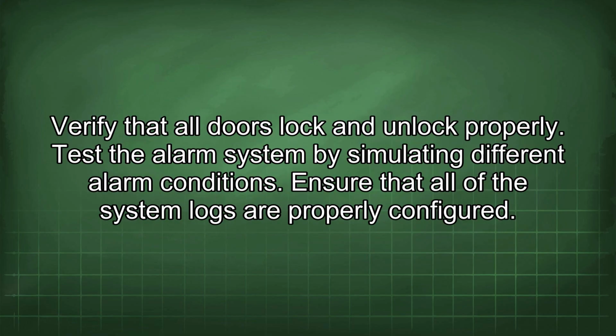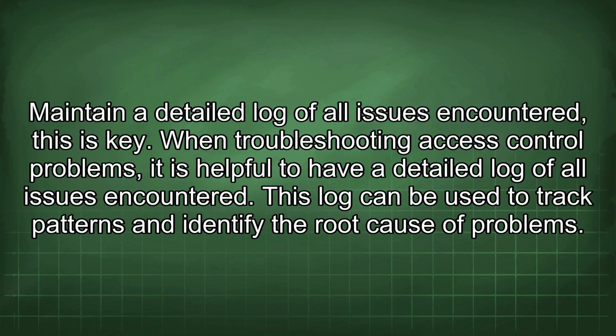Verify that all doors lock and unlock properly. Test the alarm system by simulating different alarm conditions. Ensure that all of the system logs are properly configured. Maintain a detailed log of all issues encountered.